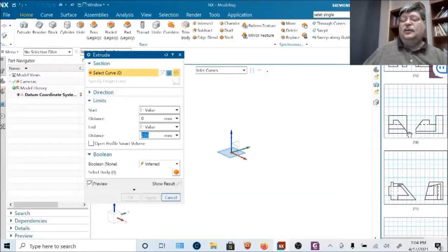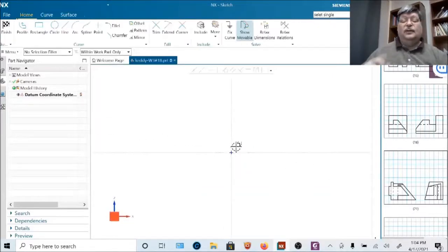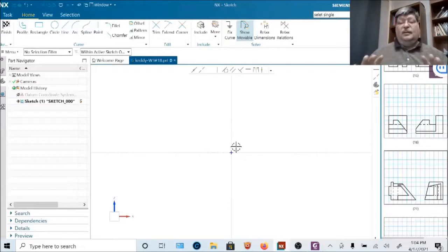So I'm going to make this back rectangular box. That's in the back. That's what I'm going to do first. So I'm going to pick a vertical plane facing forward, or the frontal plane, and click. Notice it rotates it now. I am looking at the front of the plane. It's facing me, the frontal plane.